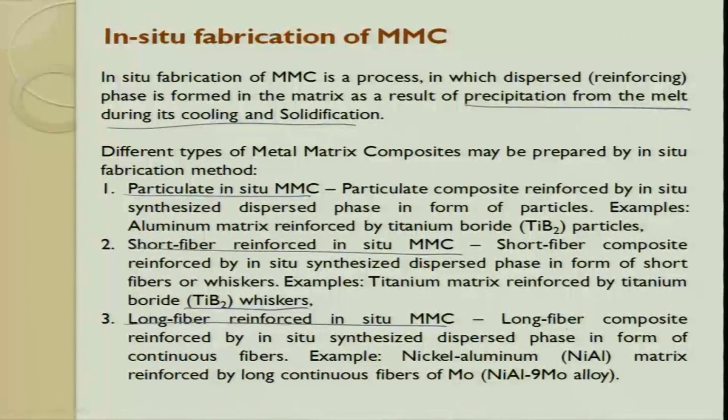Then you can also have long fiber composites, where the dispersed phase is formed in situ in the form of continuous fibers. We get metal matrix composites of nickel, aluminum and NiAl matrix. These are all matrices which find a lot of applications in the aerospace industry.